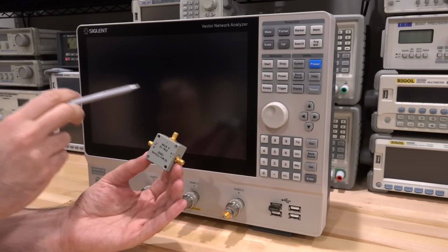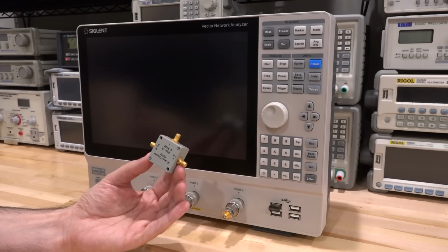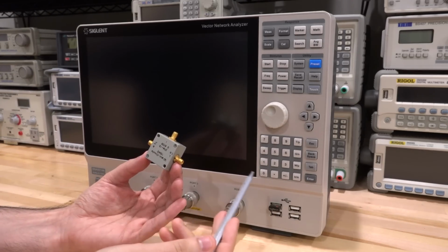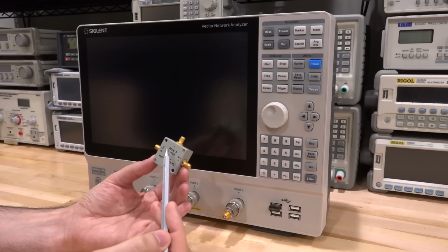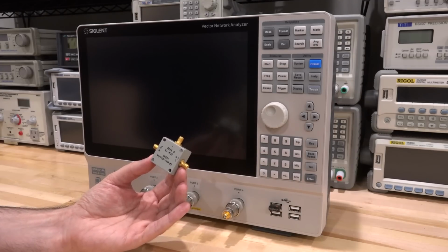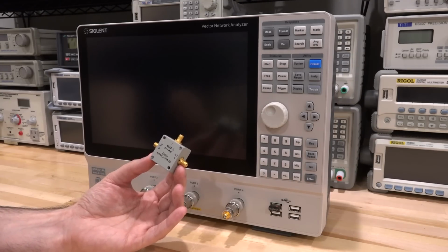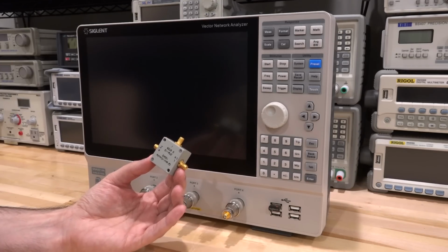That's because the RF and LO sources inside the network analyzer are going to be so tightly coupled in frequency in order to create the IF required for making S parameters. But if I have an independent source, now I can tune that independent source anywhere I want and therefore move these frequencies with respect to each other in a much more free way, allowing me to actually measure conversion characteristics. In fact, there is a license for this instrument that allows you to make the vector measurement of that too. We'll talk about that in a second.